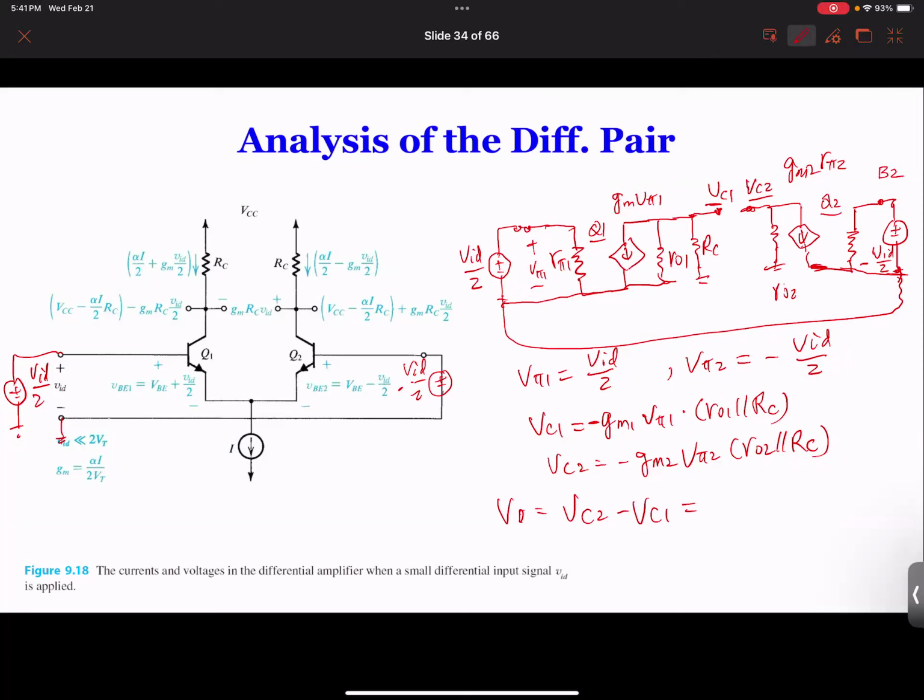Yeah, you are right. But eventually, since later on we'll find everything over there is ground, we'll just simply connect everything like this to a ground. Yeah, because it is a virtual ground. It's not physical. You're right. So it's a little bit different between a physical ground and a virtual ground. A virtual ground is, by mathematical calculation, at potential 0, but it's not actually physically connected to the ground.